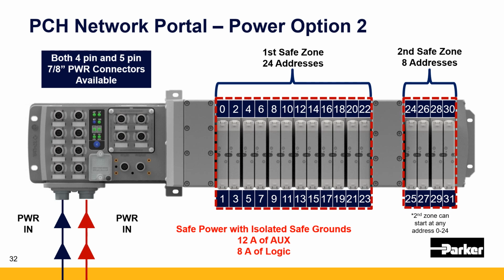And whatever is left over, you guys have at your disposal on the rest of the plant floor, that is up to 20 amps. So we really love that this offers you that flexibility in your power architecture, allowing you to simply daisy chain your power in the same way that you daisy chain your network communication, right?